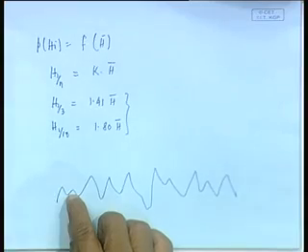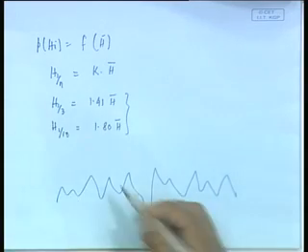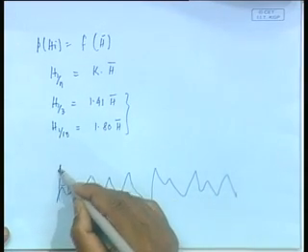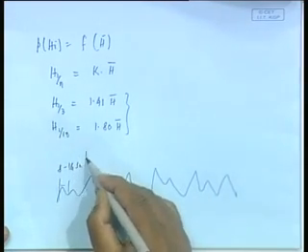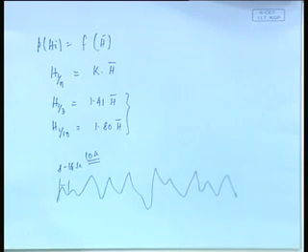If I want to have statistics, I want to tell you another thing here, that you see this average period, that is how much? About 10 seconds. If you see this time period, around 8 to say 14 seconds, say an average of 10 seconds, let us say. So if I collect 1 hour of data, how many peaks do you expect approximately? 1 hour is 3600 seconds, so around 360. So if I collect data continuously, then what will happen? I will end up getting a very large data set.